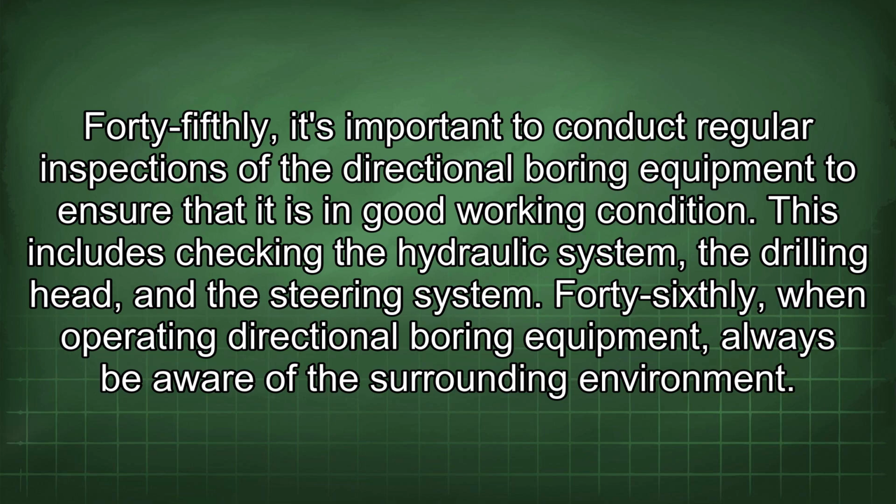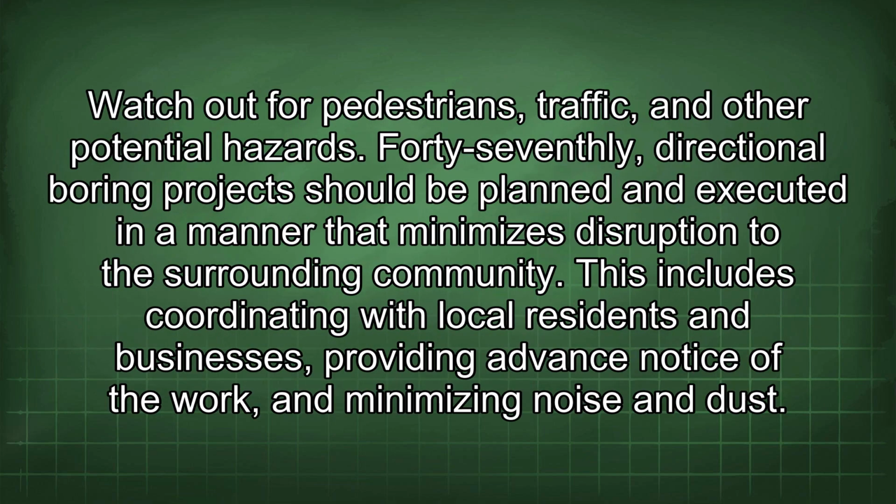45thly, it's important to conduct regular inspections of the directional boring equipment to ensure that it is in good working condition. This includes checking the hydraulic system, the drilling head, and the steering system. 46thly, when operating directional boring equipment, always be aware of the surrounding environment. Watch out for pedestrians, traffic, and other potential hazards. 47thly, directional boring projects should be planned and executed in a manner that minimizes disruption to the surrounding community. This includes coordinating with local residents and businesses, providing advance notice of the work, and minimizing noise and dust.